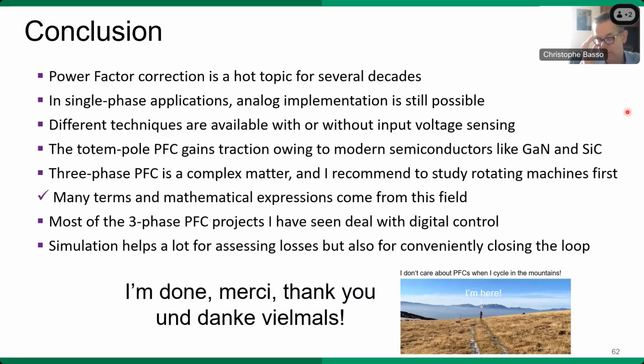Why? Because in the compensation path, people would like to integrate as much as they can the compensation elements. However, because of the fairly high time constant, it's difficult to reproduce these time constants in an analog way. So what people do is they hardwire a digital compensator inside the chip, where it saves you from having external compensation elements, and it's a more or less plug-and-play type of circuit.